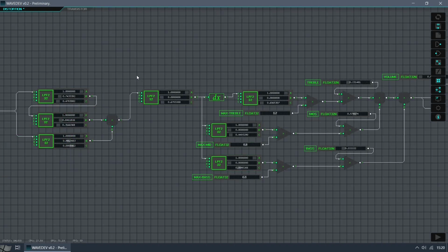Now it's time for the standard 3-band equalizer. Everyone is already familiar with this. I'm implementing a very rudimentary EQ, not more than basic analog passive filtering. In fact, I'm using the same ideas from the old distortion pedals. Here we only have first-order filters. No resonance. A low-pass filter to limit the high components. And 3 branches for high, mids, and lows.